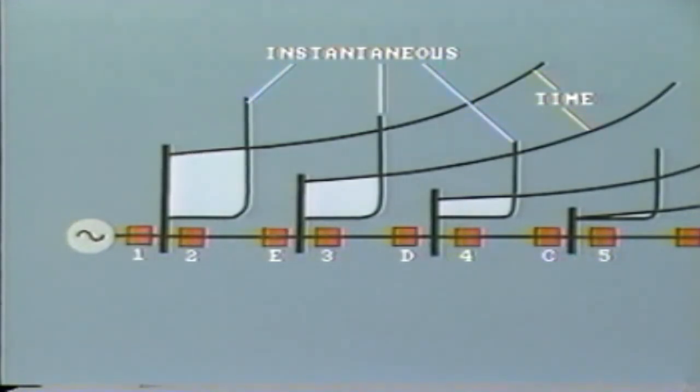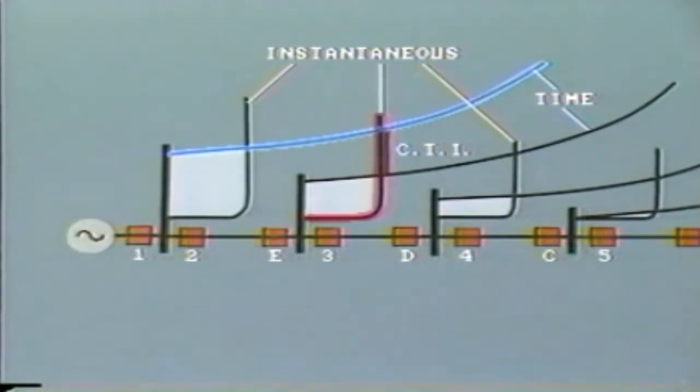There is another incidental advantage. The upstream time overcurrent relays can now be coordinated with the downstream instantaneous relays. Thus, the new coordinating time interval is this distance here. So the time curves can be lowered with lower time dial settings, thus reducing tripping times.